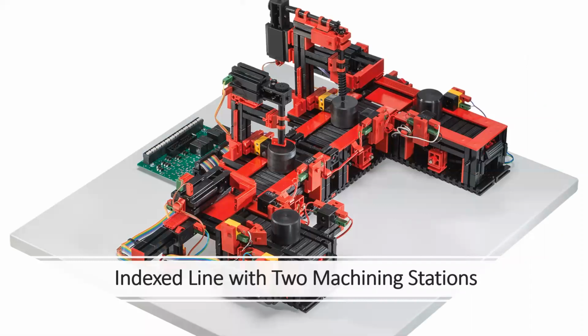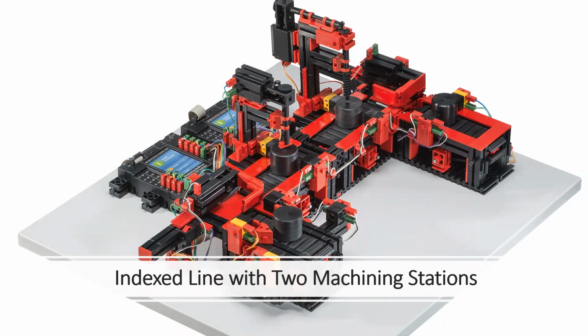The next model is the indexed line with 2 machining stations. The model features a U-shaped conveyor line consisting of a milling and a drilling station and 4 conveyor belt sections. Components of this model include the 4 conveyor belts, just as I mentioned, 8 excess motors, 4 push-button limit switches, 5 phototransistors, and 5 LED light barriers. The dimensions of this model are approximately 19 by 18 by 11 inches with a weight of about 8 pounds. And again, it's available in both the 24-volt version for use with PLC and a 9-volt version wired to the pre-programmed robotics TXT controllers, 2 of them in this case, and requiring one 120-volt power adapter.